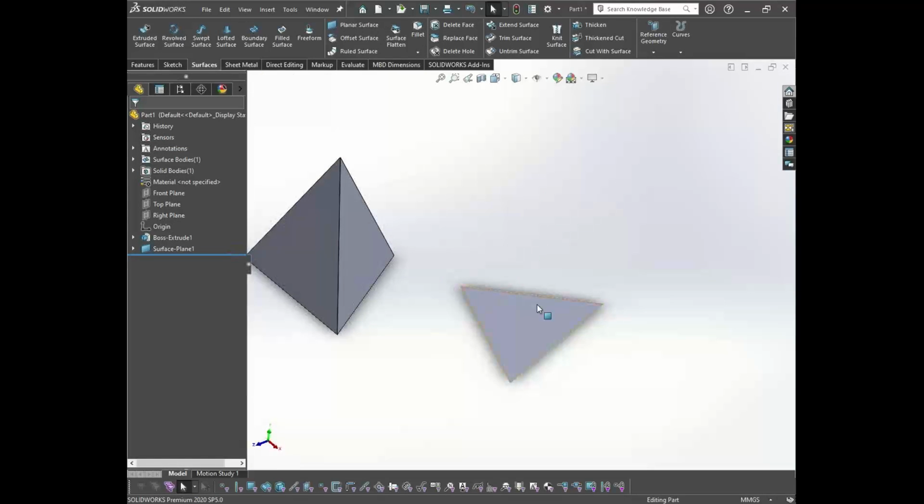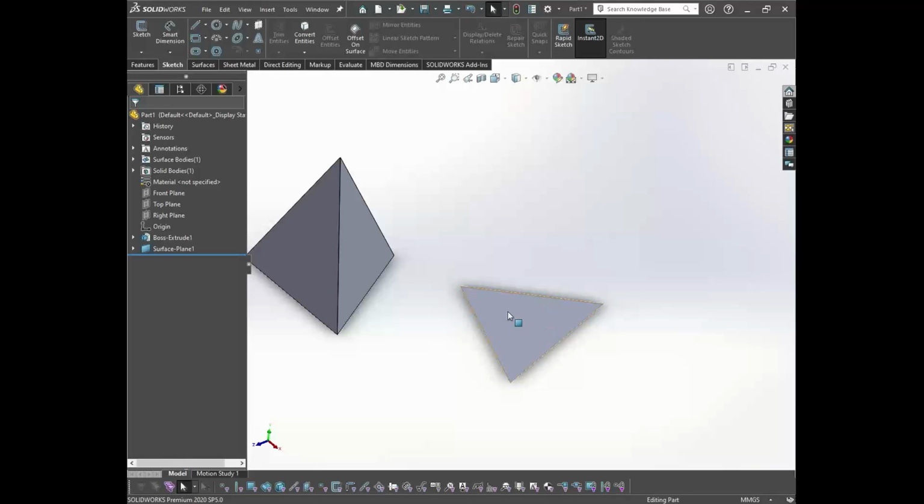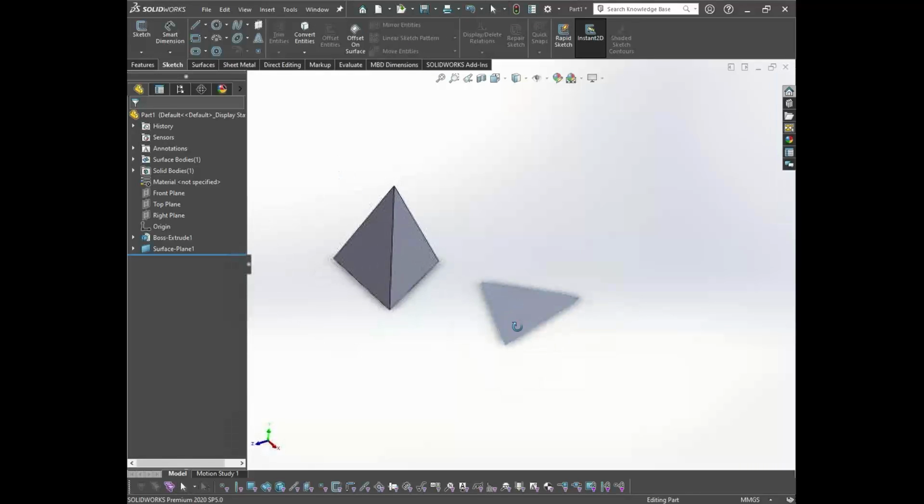as I've told, whenever we are dealing with sheet metal components which have uniform thickness throughout their length, that is, the cross section is uniform, you can consider the shell elements for those particular examples. I think you must have learned about sheet metal in the previous training session. If you perform any kind of sheet metal operations and make the geometry with the help of sheet metals, when you import it into SolidWorks Simulation, you get the shell mesh directly. So after performing the meshing, you'll get the shell mesh.